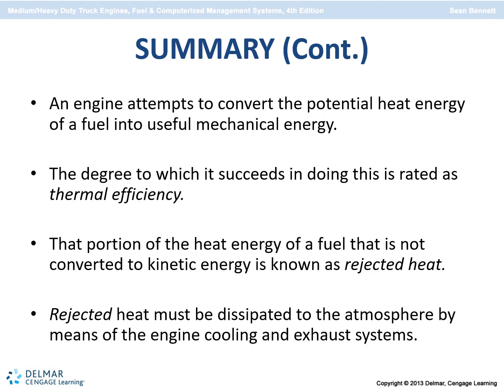The engine attempts to convert potential heat energy into useful mechanical energy. This is known as thermal efficiency, and the heat energy of a fuel that is not converted into kinetic energy is rejected heat. That's approximately 60% of the fuel's energy. Rejected heat must be dissipated by methods of cooling and exhaust.